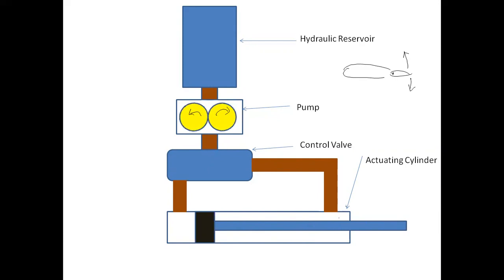It will operate the control surface. This is connected to your aileron. So when this is being pulled inside or when it is being pushed outside, the control surface will either move up or down. It can also be connected to other important components like landing gear, elevator. So everything can be controlled by the hydraulic system. So here what is happening? The high pressure hydraulic fluid is coming into the right side of an actuating cylinder.